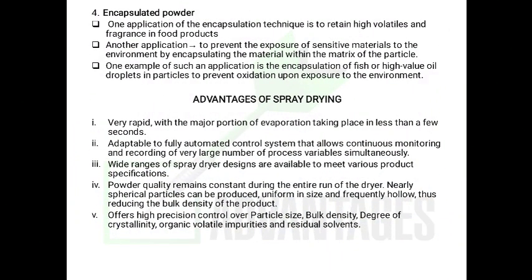Encapsulated powder. One application of the encapsulation technique is to retain high volatiles and fragrance in food products. Another application is to prevent the exposure of the sensitive materials to the environment by encapsulating the materials within the matrix of the particle. One example of such an application is the encapsulation of fish or other high-value oil droplets in particles to prevent oxidation upon exposure to the environment.